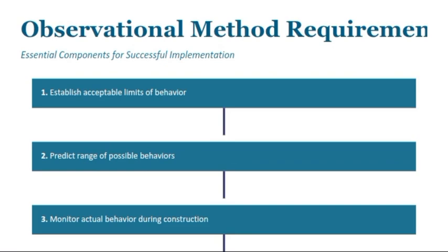Like we said, there has to be intervention if things change. So even when you predict there can be change, you should have a pre-planned corrective action. If monitored values exceed acceptable limits, the engineer must already know what corrective measures to implement. For example, ground improvement, additional drainage, structural reinforcement, or construction modification altogether. Without pre-planned actions, monitoring becomes useless. What's the use of monitoring if you don't know what to do? The engineers will just observe problems without knowing how to respond.